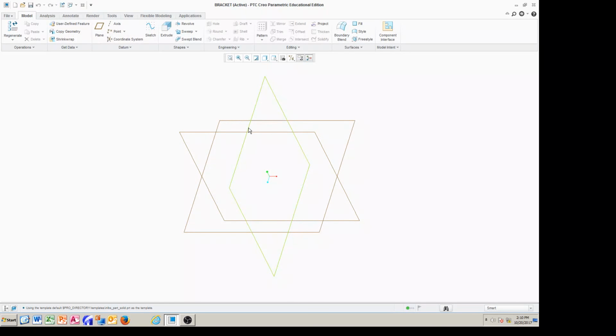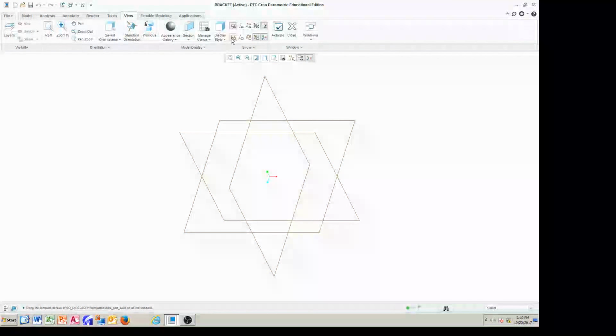And now we are in the area of sketching. We're going in a part mode where we are going to use the plane called the frontal plane to create this solid model. So I'm going to turn on all the name tags: front, top, right side view. In order to do that, you go to view and then click on this icon or command called plane tag display.